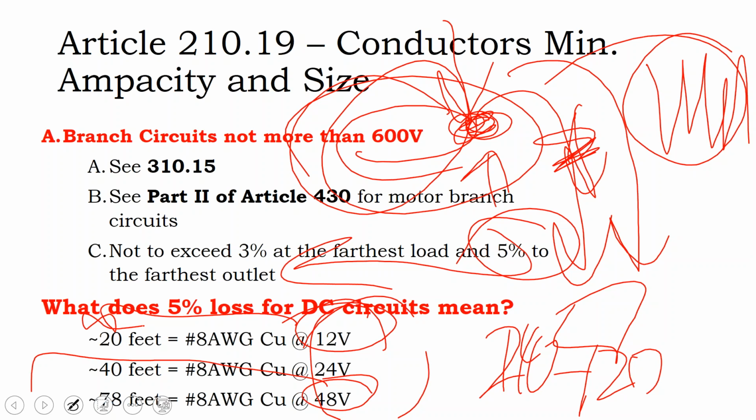And so, while a DC circuit might work for a tiny house, a hunting cabin, or an RV, you might specify DC circuits in your home, but they might just be around the battery room itself. So you might do a DC water pump, a DC heating element, or a DC air conditioner in the battery room itself, and have DC circuits. It's just not standard.